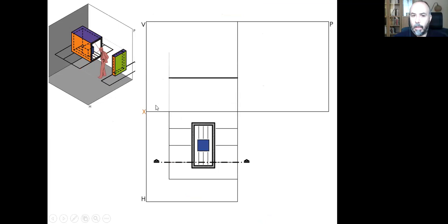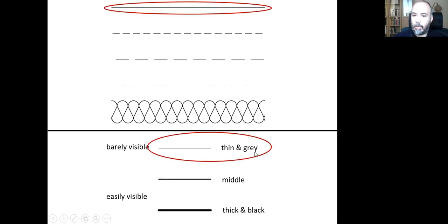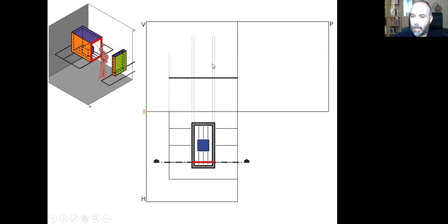And after that, I need to check if there is anything cut here in the object, and I see that the prism is being cut. So I need to draw this, and here it's this surface, the intersection of the vertical cutting line and the prism here. So I need to transfer these with 2 millimeter thicknesses up here with, again, thin and gray lines as my guiding lines.